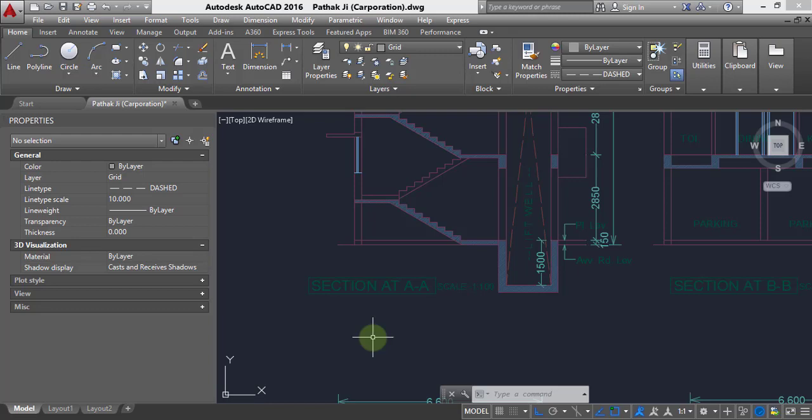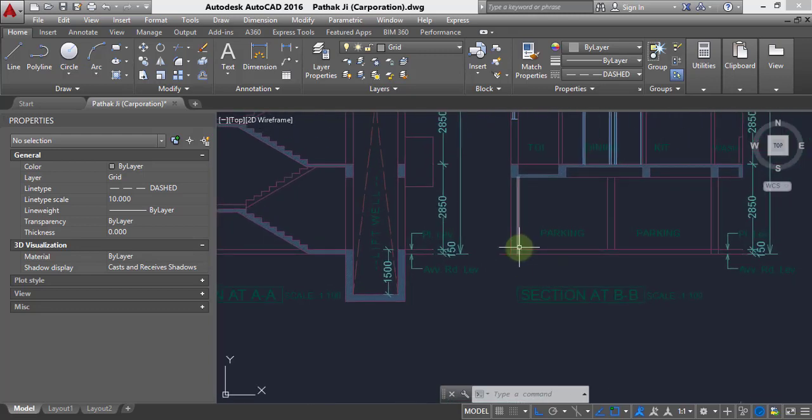Now, to avoid this, you provide plinth beam at the ground level, so that it decreases the unsupported length of the column. Thereby, it will increase the capacity of column against buckling, and also it is going to decrease the moment in support, and ultimately it is going to result in economy in design of column as well as foundation design.